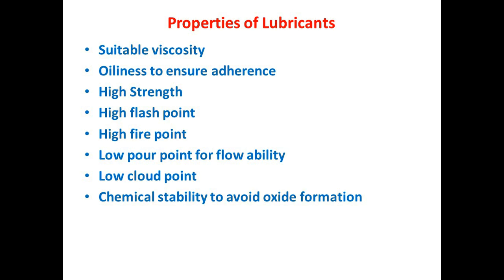Viscosity is inversely related to temperature. If temperature increases, the viscosity of the lubricant decreases, and if temperature decreases, the viscosity of the lubricant increases. So, for better oil selection, you have to identify the oil which has a high viscosity index number.